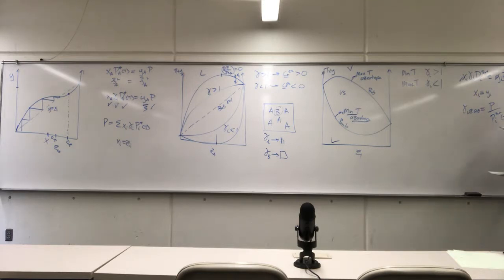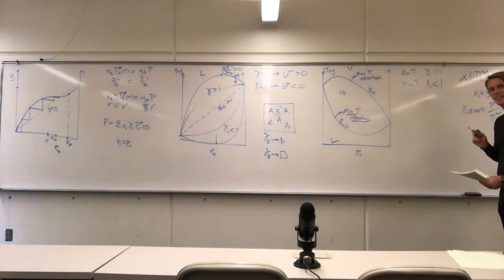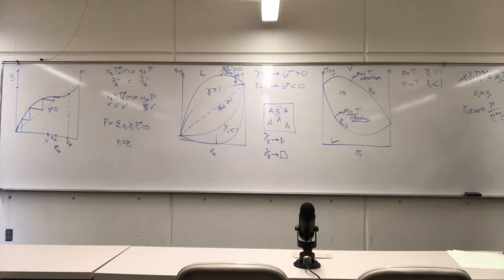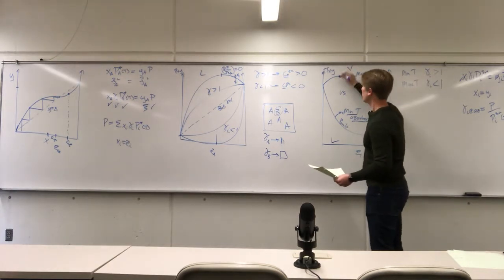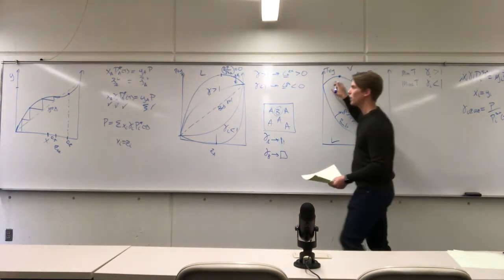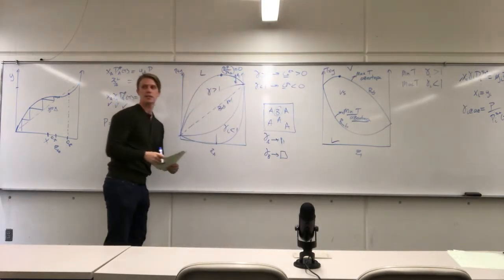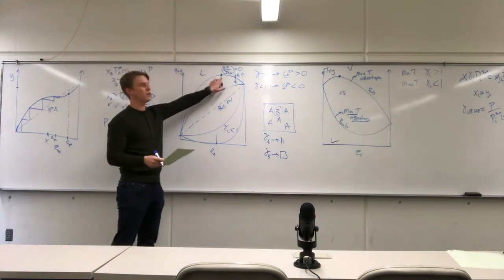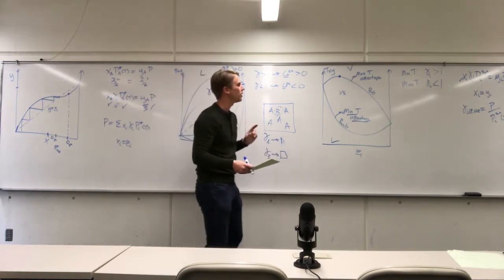Does that make sense? It's a bit more complicated because the activity coefficient is a function of temperature and the vapor pressure is a function of temperature, so you have to assume temperature. Yes, but at the pressure and temperature of the azeotrope, for example. So if we have a particular azeotrope right here, and the TXY, again, that's why it's not trivial to do so, rather it's easier to do it here. Right, so with the pressure, for the temperature being constant, this is where you would tune the azeotrope, so tune the activity coefficient model.